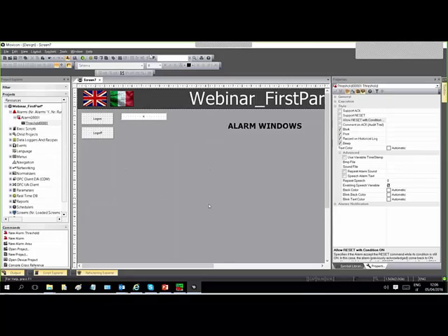It means that it's not an alarm that requires the operator to acknowledge and reset, but a message that appears and then goes away automatically when the condition re-enters. For example, missing communication is often managed in the plant as a message. It's not something that you can acknowledge and reset. It's a condition that, when present, is still present until the condition goes away, and does not require a direct action of the operator.